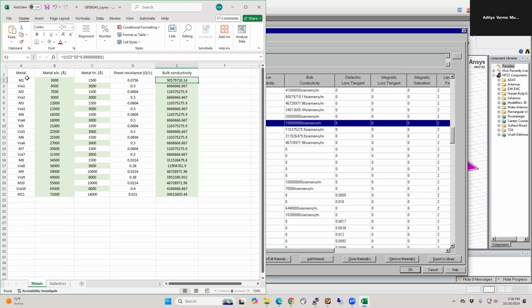In a future video, I'll talk about how to do that because in that model, you have to include the via conductivity as well. And to include the via conductivity, you need to know what kind of via density you can have. And that depends on the DRC rules. So once we go through DRC and LVS, then we will see how to make these kind of grids that we need for high frequency. And from those grids, we can extract what would be the effective bulk conductivity of composite metal layers.